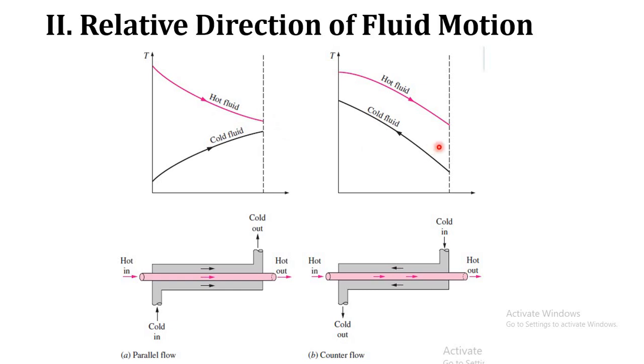But in a counterflow heat exchanger, the exit temperature of cold fluid may be higher than that of hot fluid. This is the exit temperature of hot fluid, and this is the exit temperature of cold fluid. Here in a counterflow heat exchanger, there is a chance that the cold fluid exit temperature will be more than that of the hot fluid's exit temperature. This point, please keep it in mind.